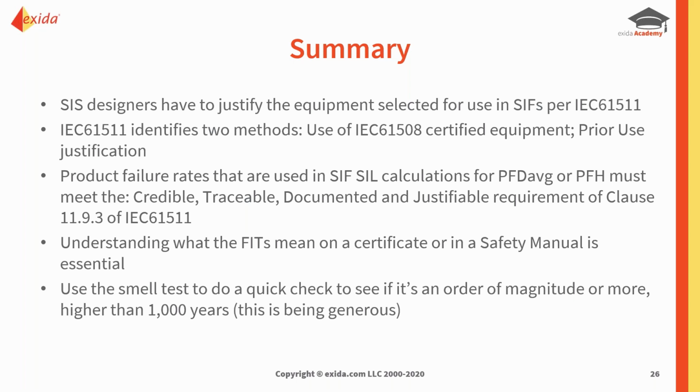Understanding what the FIT or FITs mean on a certificate or in a safety manual is essential. And here again, we've seen oftentimes end users don't have the safety manuals because the engineering company didn't supply it. Well, as an end user, you are entitled to have that safety manual. And so the engineering company needs to supply that because the safety manual has certain information that's very relevant for your ongoing maintenance and health of your SIF and SIS.